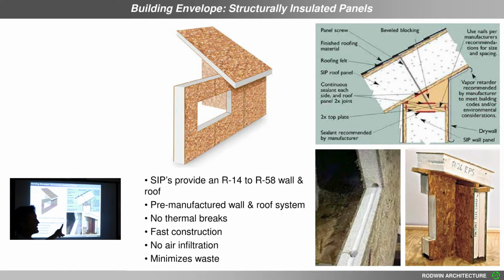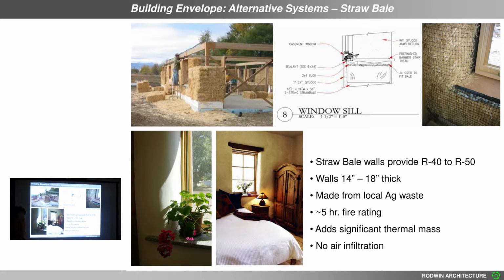The thing about these products is that they have the ability to off-gas most of the volatile organic compounds before they reach your house, meaning they're not interior finishes. There are certain things like the floor finish or cabinets that tend to go in towards the very end, once the house is already sealed up. Things like OSB tend to be happening when the house is wide open. You don't even have windows in, so the house is able to off-gas most of the toxic chemicals into the air. How many months would you say?